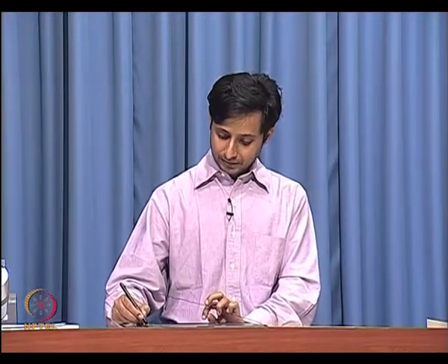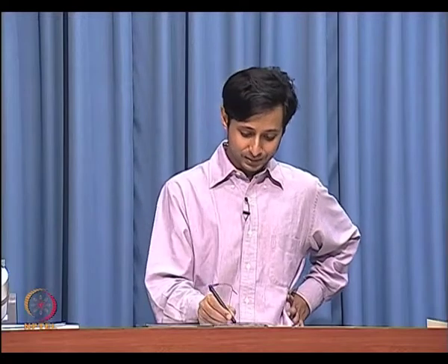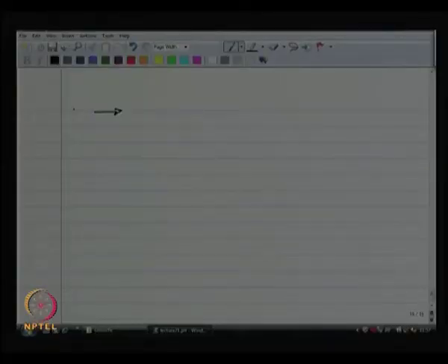So, this is my motivation to build a low noise amplifier. A low noise amplifier does not reduce the noise that is coming from the signal. It is not possible to reduce the noise. The signal already has some noise in it, you can't get rid of that noise. What the low noise amplifier is going to do is make sure that compared to the noise in the signal, it is not going to add much more noise by itself. That is all that I can do. So, the signal at the input of the low noise amplifier already has noise.